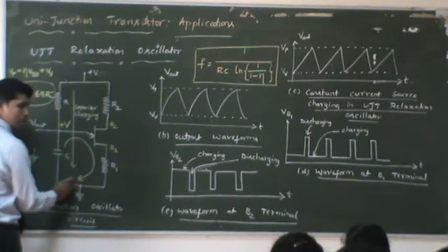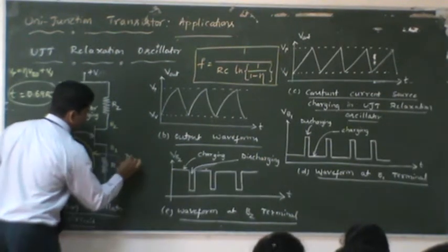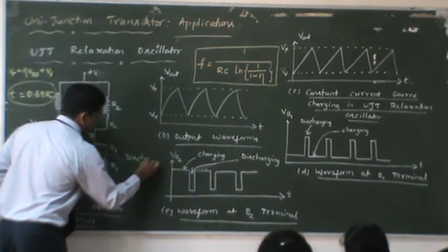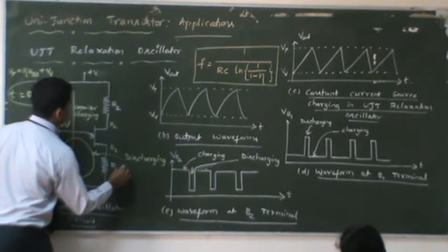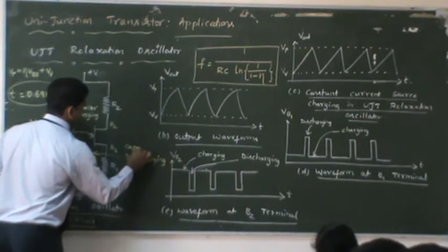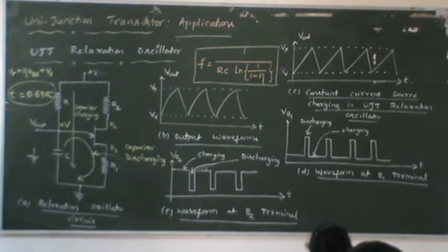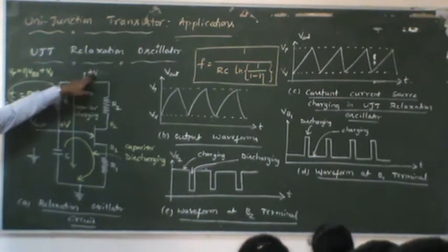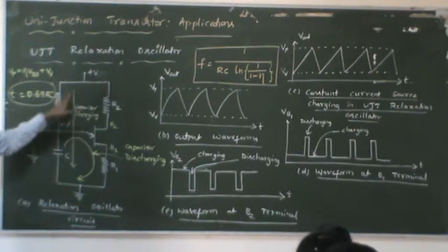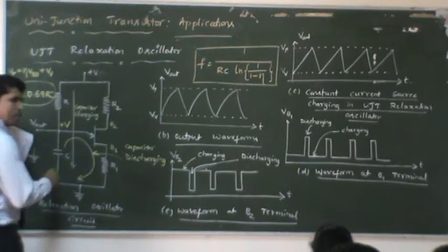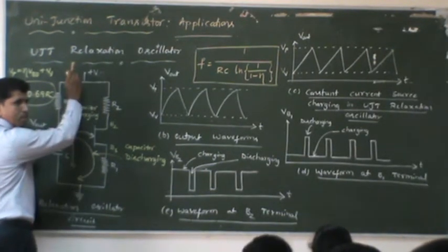This loop is nothing but the discharging loop. We mentioned here, this is a path which shows the capacitor discharging. You can also identify the paths. The capacitor charges through the plus V, R, and this particular capacitor. This is a charging path, and the capacitor discharges through R, because again, the current cannot go to the supply itself.